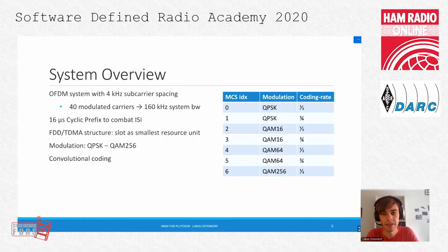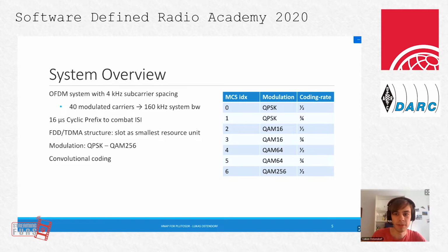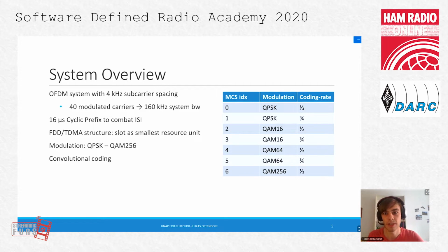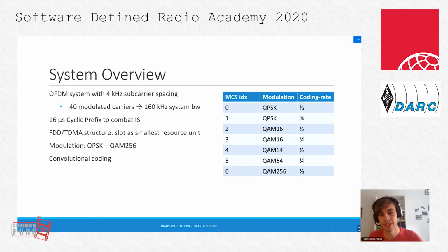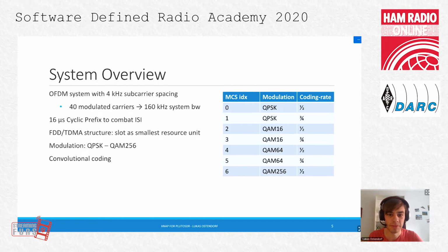When we use TDMA instead, only one client transmits at a time. So if, again, this bad client with a nonlinear amplifier appears, the client will have a bad connection, but it won't affect any other users. And since we cannot guarantee that everybody uses certain amplifiers, because in the end it's the amateur radio community, so probably many will use their own amplifier, this TDMA system will be more robust.